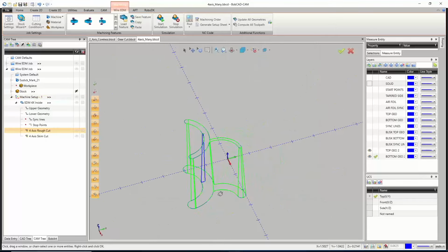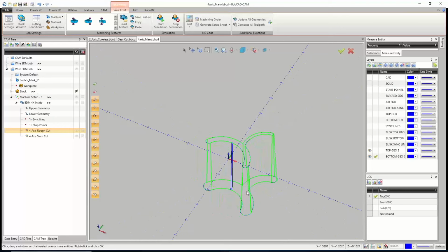And there is the taper. Now there's no land on this one. It's not something I added in. You could just do a straight cut if you wanted to now. It's no faster or slower. I mean, it's slower than doing a land and taper. But the benefit of this one is if you don't know what the taper angle is. We got lucky a few minutes ago. I just guessed it at 2.5. It could have been 2.47 or something weird. If you don't know it, this is probably the best way to go about getting it, because this one's going to kind of calculate that for us.